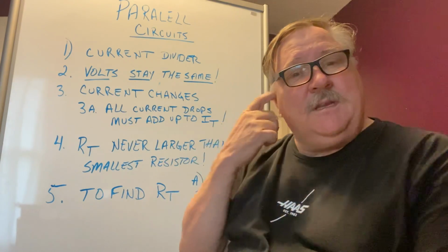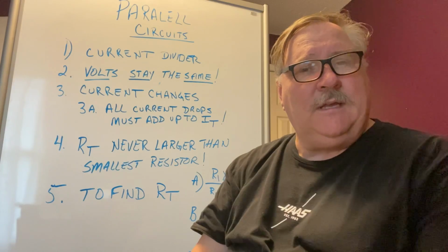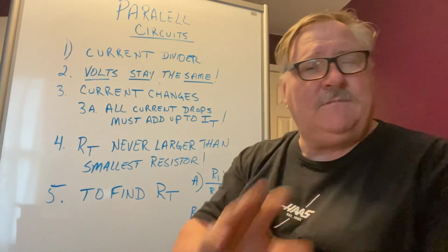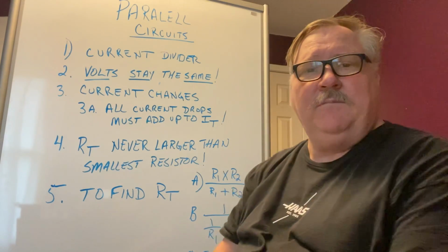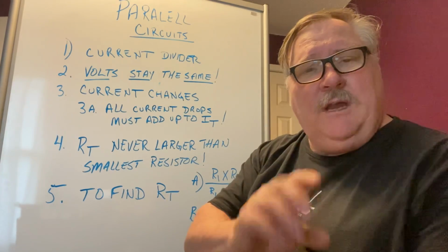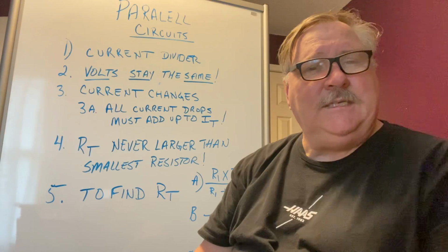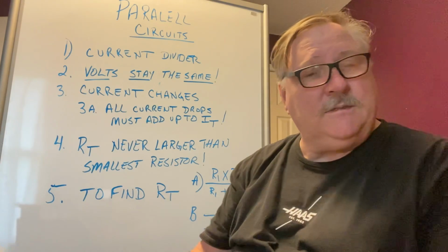If I plug something in on the next wall over, I'm probably going to have my circuit breaker tripped because I'm over current on that. Okay, but we'll get into that kind of stuff later. But my point is, that's one of them. The other one is your car. Everywhere you check on your car, you're going to get 12 volts DC on that. In the residence, it's AC voltage.